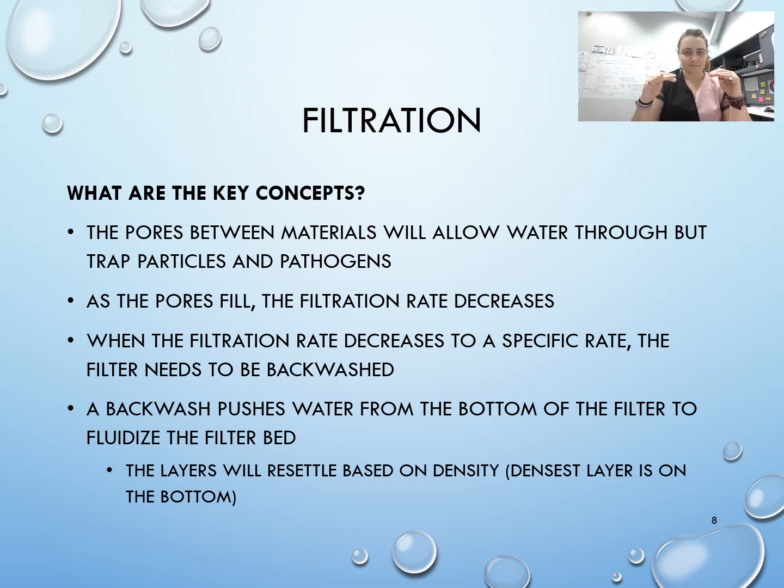What a backwash does is it pushes water from the bottom of the system and it fluidizes the filter bed. And so all of the material comes up, the nasty, dirty water comes to the top and it's drained off the top, and then the filter media is allowed to settle.